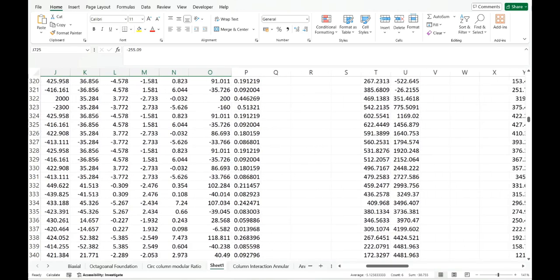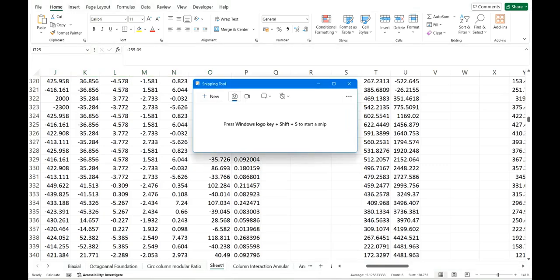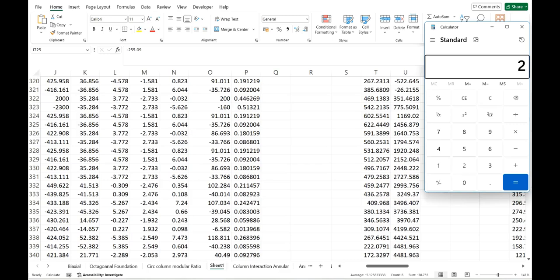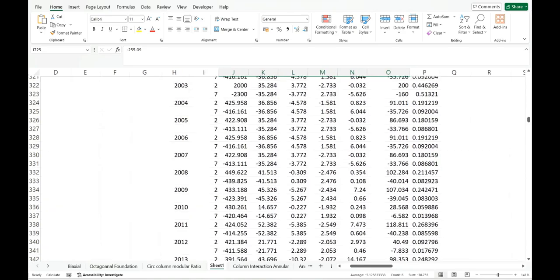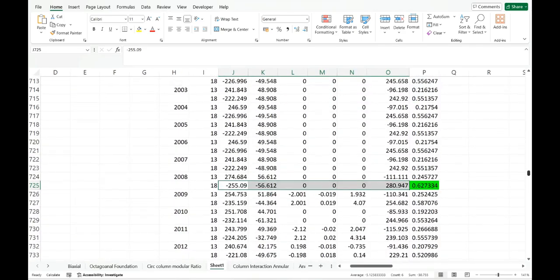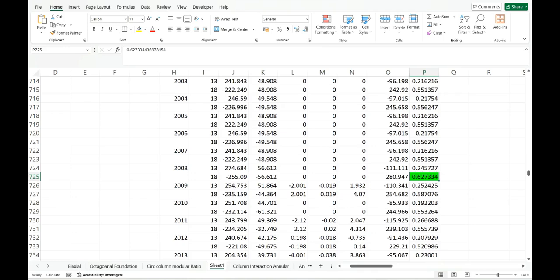Now here we have 255 between, say, 385 and 351 and 26, so it could be something to the tune of maybe 410 or 420 kilonewton load. Now we have a load of 255, so 255 divided by 410 or 420 roughly gives 0.62. That is the number we are getting approximately. This program is working it out more rigorously, and we are getting 0.63, which seems to be in close agreement. So ideally, this is what our program does for the calculation of the column interaction charts.